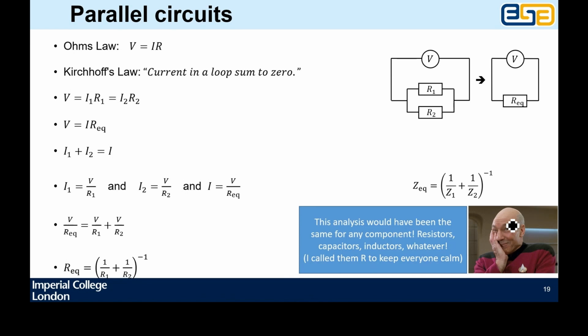So the key thing is that this doesn't just apply to resistors, this applies to any reactive components. Okay, so in general, the equivalent impedance of a parallel pair is also 1 over the sum of the 1 overs. Okay, so ZEQ equals 1 over (1 over Z1 plus 1 over Z2 plus 1 over Z3 plus 1 over Z4) if you wish. Okay, so they just have this inverse sum property, parallel resistor sum.